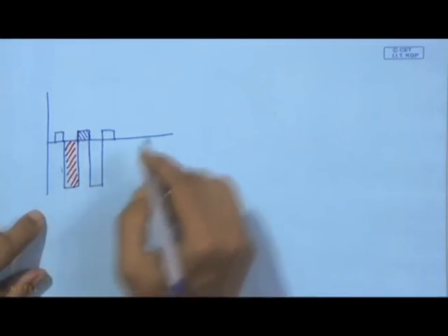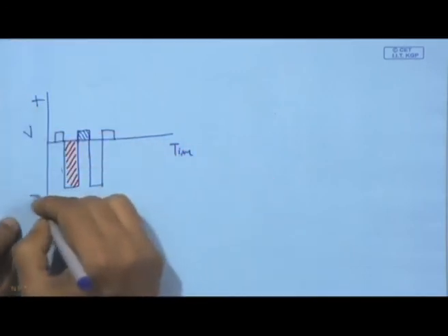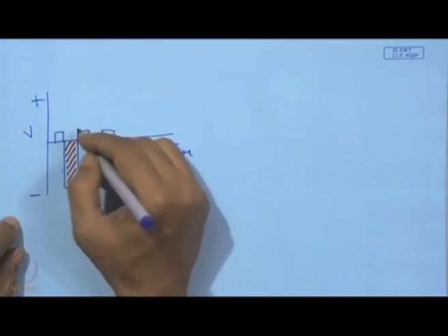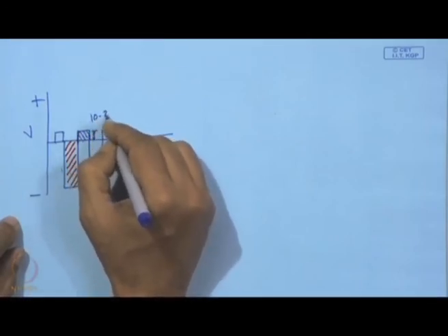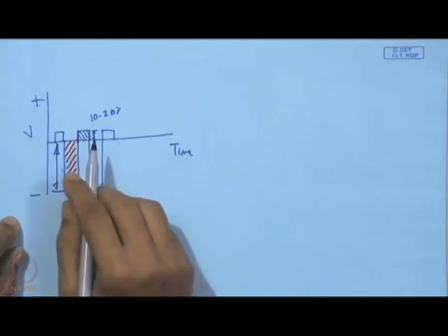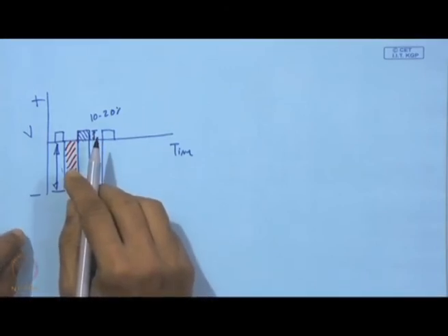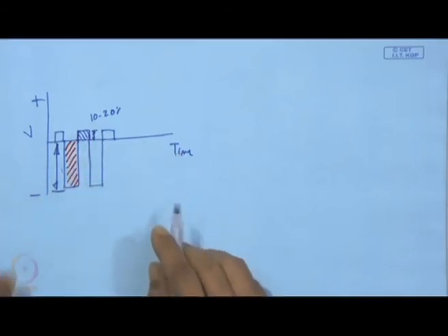So, this is single magnetron with bipolar pulsing, but here this positive polarization, that magnitude, maybe it is around 10 to 20%, this is time and this is voltage plus minus. This part may be just this magnitude, maybe just 10 to 20% of what we put here, and that is good enough to ensure that the total charge is totally neutralized by this positive polarity.